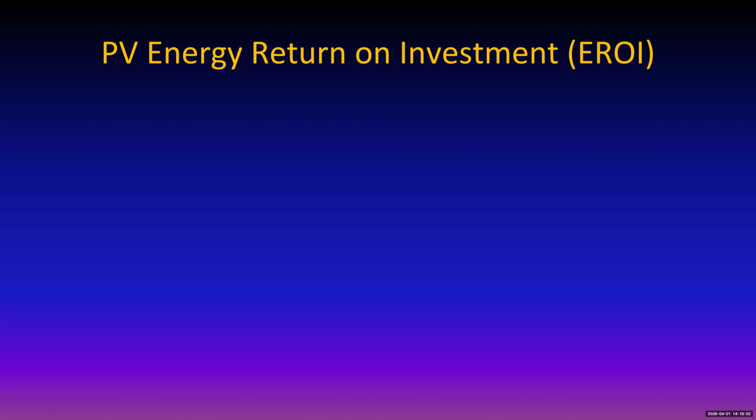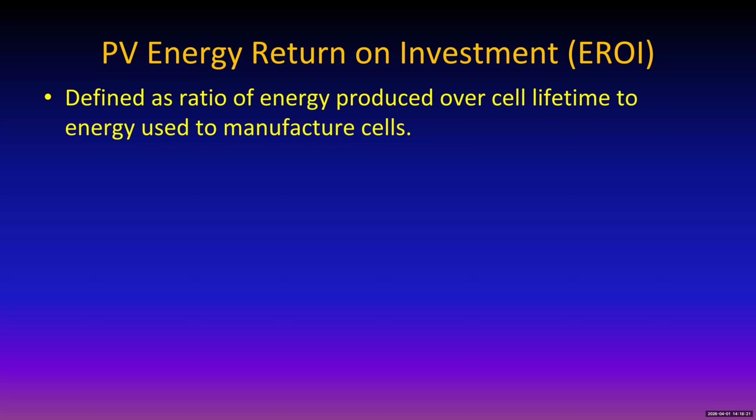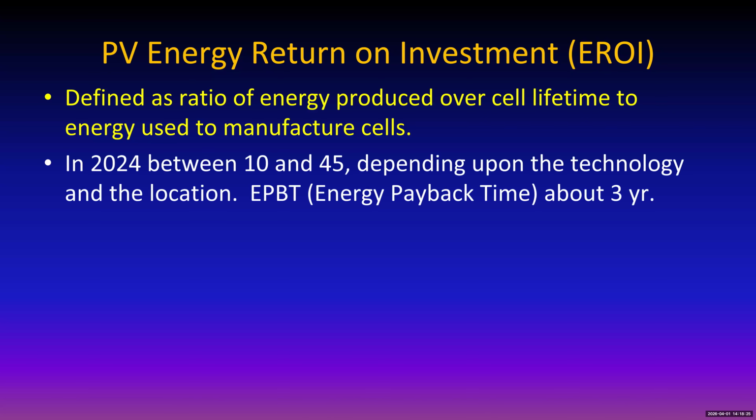So in any case, the energy return on investment, if it's greater than one, that means if your solar panel will generate 2 kWh for 1 kWh that is expended in creating it and installing it, then it's a good investment. So here are the numbers: the energy produced over a cell lifetime, versus the energy used to manufacture the cells, and in 2024, these numbers were somewhere between 10 and 45, depending on technology and where you located it.